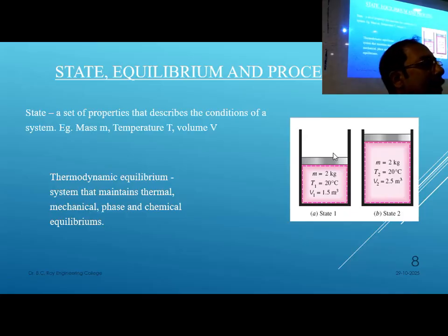Now there is another one called steady state. What is steady state? Steady state means some material is coming in and the same amount of material is going out. Maybe from a water tank, water is getting filled in and water is going out through some other outlet. In that case, the rate of filling of the tank and the rate of the outlet become equal. Then we call the system to be in a steady state condition. So mass will be constant? Yes, everything will be constant, but it is not the same water, not the same material, similar, not same. The water is flowing out.